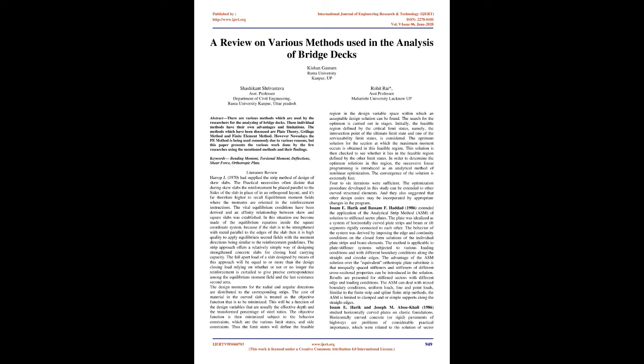Maharishi University, Lucknow UP. Region in the design variable space within which an acceptable design solution can be found. The search for the optimum is carried out in stages. Initially, the feasible region defined by the critical limit states, namely, the intersection point of the ultimate limit state and one of the serviceability limit states, is considered. The optimum solution for the section at which the maximum moment occurs is obtained in this feasible region.